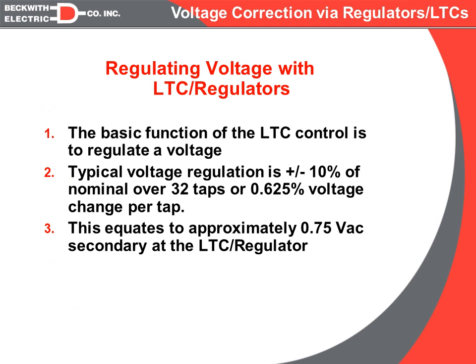The load tap changing transformer. An LTC and a regulator both function in the same way. First of all, they are what we call unidirectional, in that they change the voltage only on the load side of the device. So on the source side of the device, the voltage remains fairly unchanged. Now, all an LTC or a regulator is, is a transformer that has taps that can be changed under load conditions.